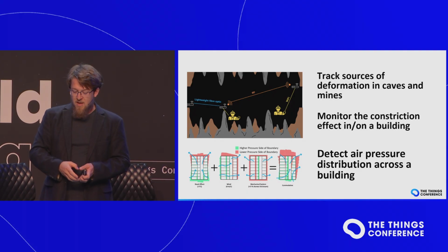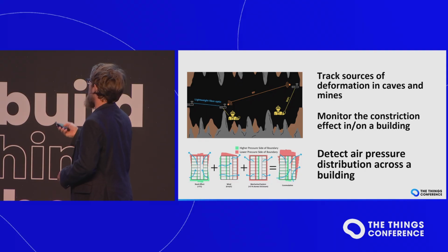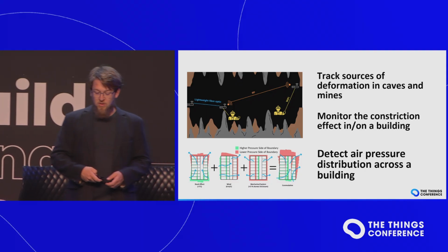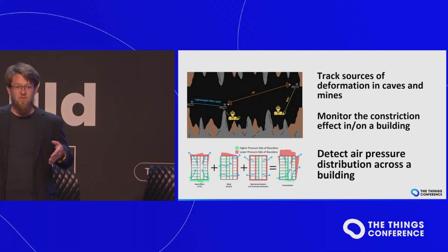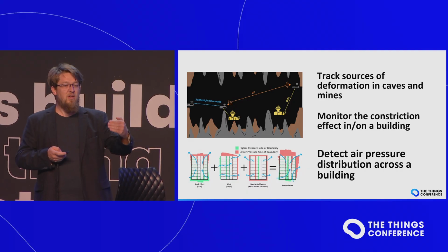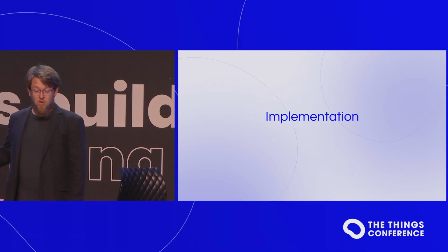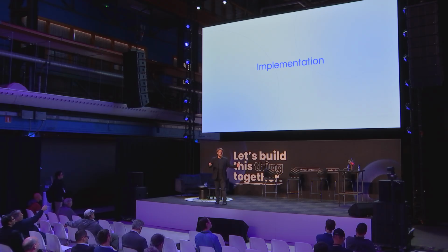from room to room. And if you have all of the data on where the air is coming in and how the wind is outside, you will get a pressure differential across the rooms, time synchronized. And then when you make a change, say in the HVAC system or something else, you will see how it reconfigures. And with the delays in propagation of the pressure, you can do quite some math and figure out how the building behaves. So we can do a bunch of all of these things, but we need to do it somehow. So here's how we go about doing it.